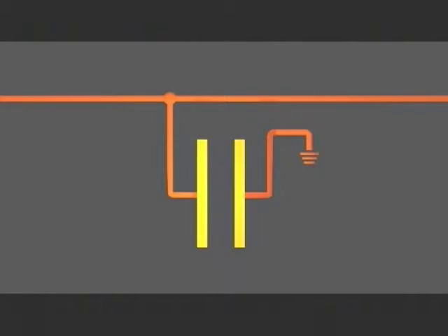Now that we know how a capacitor works, let's take a look at what it can do. If the capacitor is connected to a DC circuit, current flows into the capacitor until the plate connected to the line is at line potential. Once at line potential, no further current flow will occur other than leakage from plate to plate through the insulation. The charge will remain until the capacitor is discharged, even if the capacitor is physically removed from the circuit.